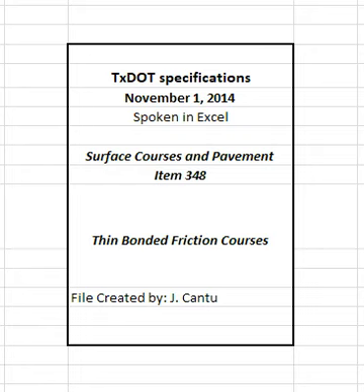2.2 Mineral filler. Mineral filler consists of finely divided mineral matter such as agricultural lime, crusher fines, hydrated lime, or fly ash. Mineral filler is allowed unless otherwise shown on the plans. Use no more than 2% hydrated lime or fly ash, unless otherwise shown on the plans. The plans may require or disallow specific mineral fillers.